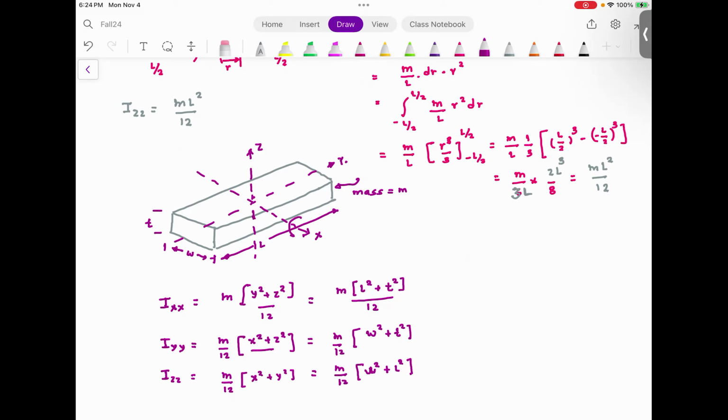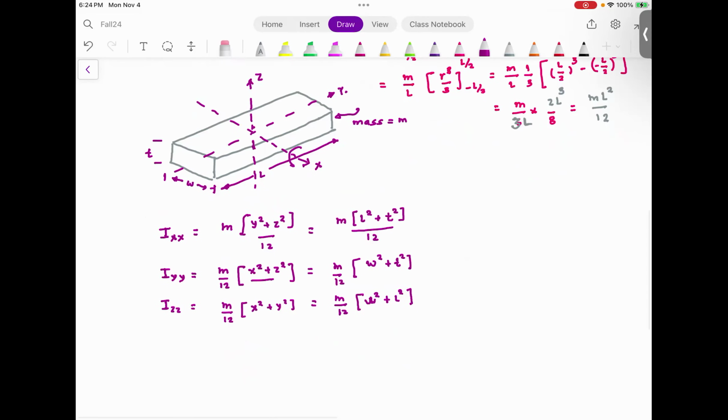Now, looking at this, one important thing to note is mass moment of inertia depends where you are taking the moment. In this case, the mass moment of inertia is about the CG. If I were to write the inertia tensor, please understand, mass moment of inertia is actually a 3x3 matrix.